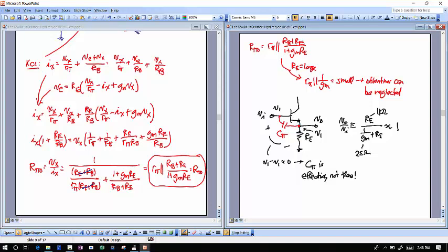So, if you're in a crunch and you're trying to determine the omega H, and you just don't have time to write the thing down, or if you're just lazy and you don't care about the 1 point or maybe 0 points you'll lose for not including it, just ignore it, right? Just take into account all the other time constants that'll be much larger than the one contributed by C pi, because C pi's got virtually no voltage across it. Ignore it. And so that's one way you can do these problems here.